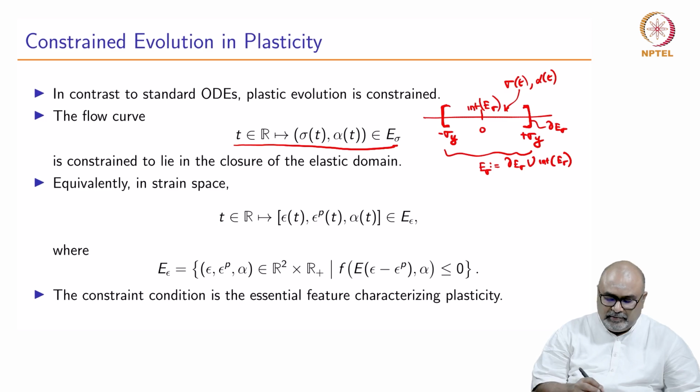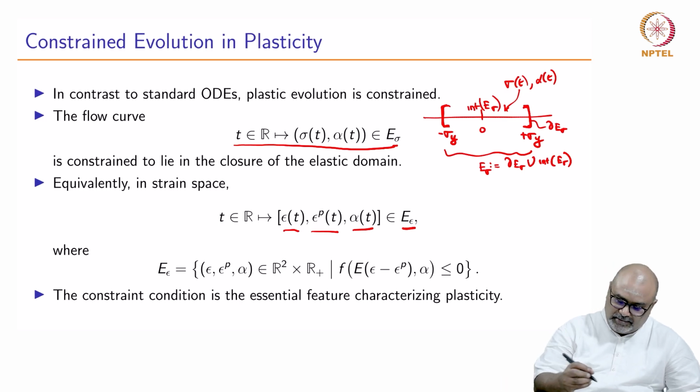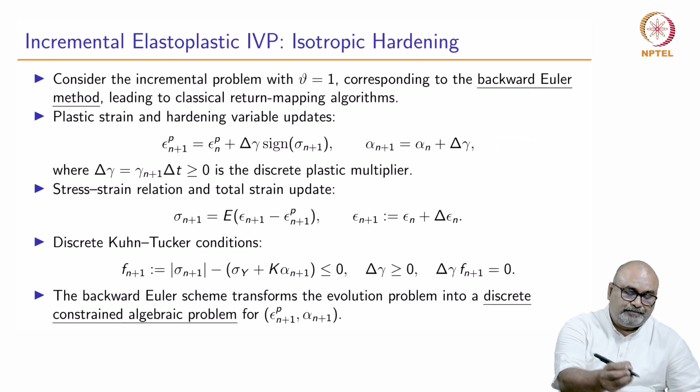Similar thing can be defined in the strain space if we are defining in terms of epsilon of t, epsilon p and alpha of t, which belongs to E of epsilon. So, either it can be a strain driven problem defined in stress space or a stress driven problem defined in the strain space. So, the constraint condition is the essential feature that characterizes plasticity.